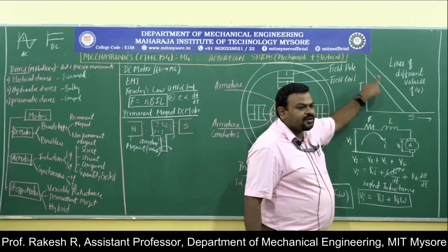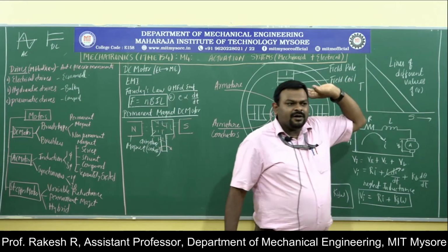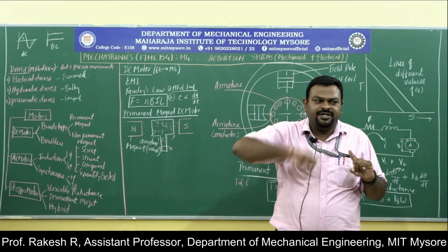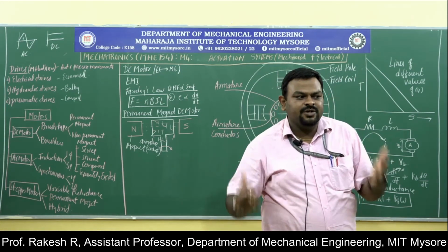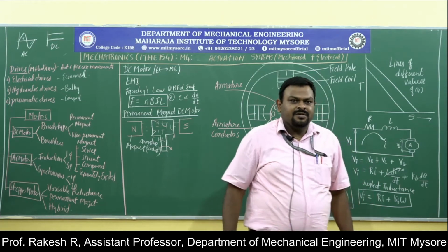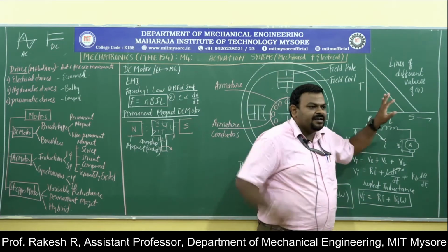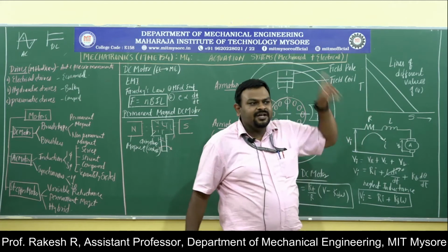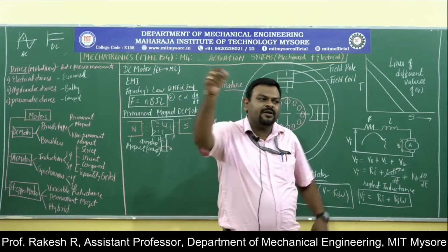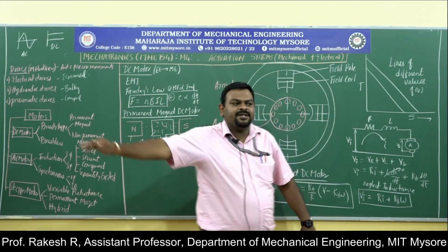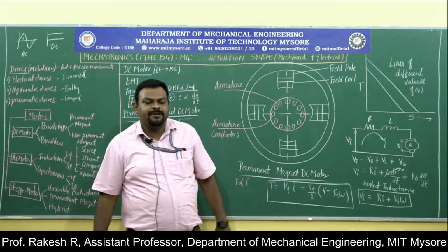After that the torque should be low, because torque means just rotation. It is a force into the rotating distance. After that I need more speed. It should rotate continuously. Initially I need more torque to overcome more inertia. After that it will be stabilized and I want high speeds later.